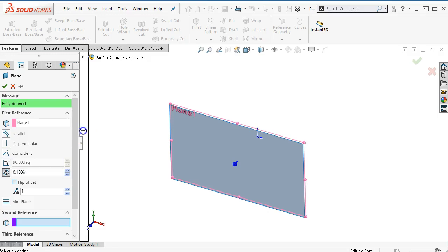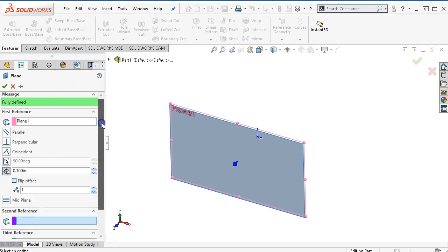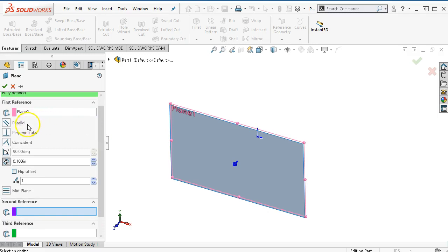Plane 1 was still selected, but notice that we have constraints: parallel, perpendicular, coincident, and then our angle and distances. Each of these requires some slightly different piece of geometry to work. Perpendicular, not so much. Parallel, maybe. Coincident, sometimes. A lot of times it'll just be distance or an angle. Angle requires that we set up a line or an axis for that plane to go through.